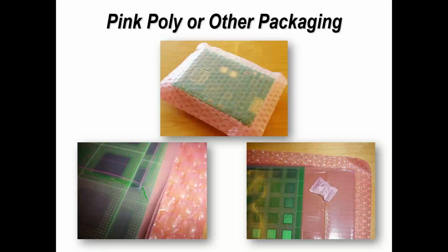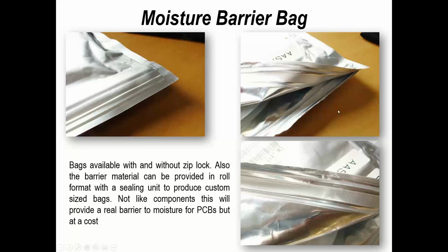So one of the other things about this type of packaging, yes, it will prolong the solderability, but it will still allow moisture to come through, and it will still allow the change in wettability or solderability of components, so of boards. So you need to still make sure that you keep them packaged as long as you can, and you'll get a certain life expectancy out of them. Now, if you pay more money, and it's all about the money, you can use bags which were designed to eliminate moisture getting inside. And these similar materials have been used for many years for components, and we all realize that.